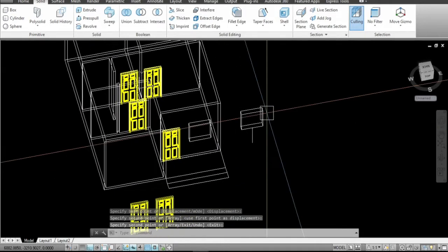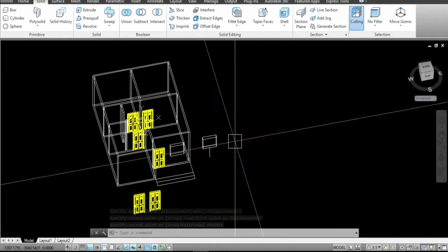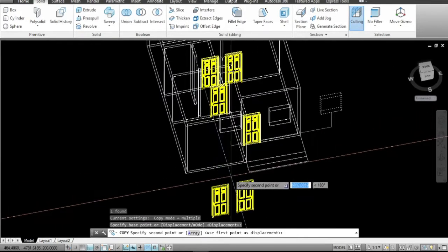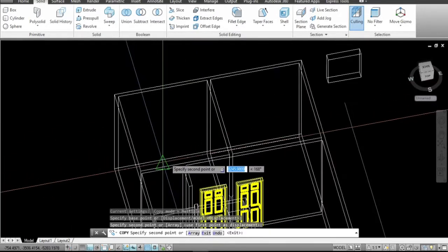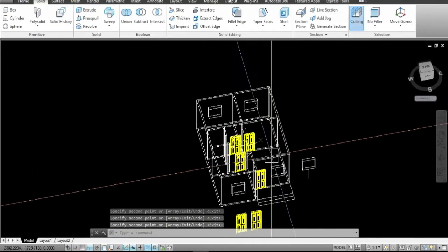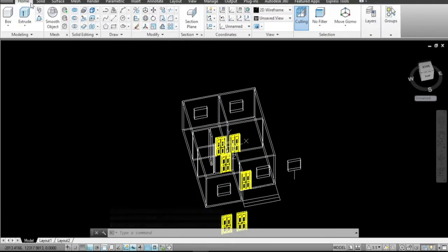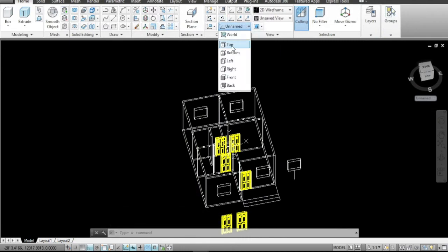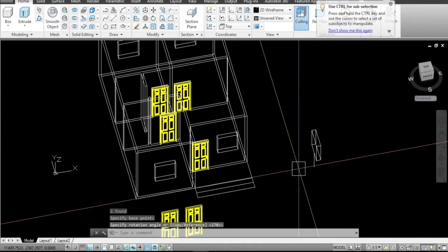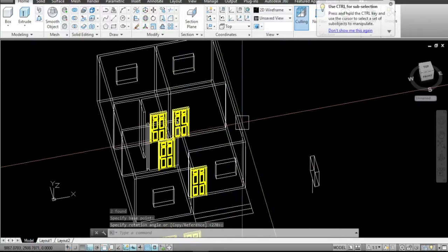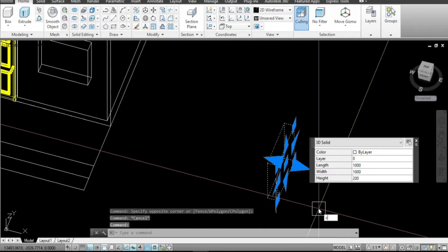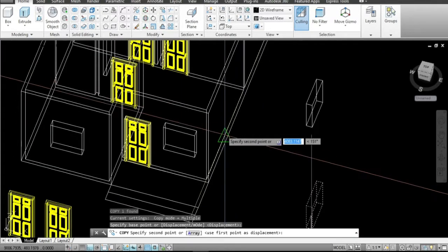Let's take a look at the 2D wireframe. So we have already put the box into the wall. Now let's repeat the copy into the different wall so that we can make a lot of windows. Now let's rotate this one for the right side window, and then copy again the box from the reference line to the center.